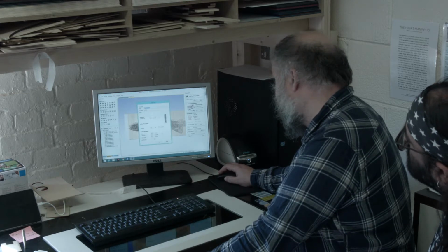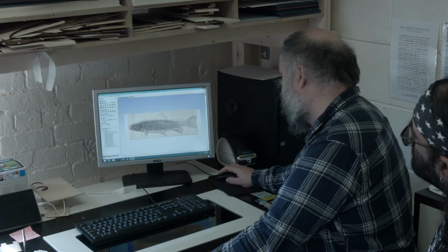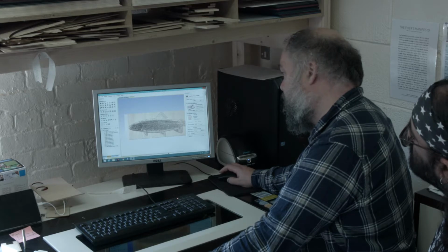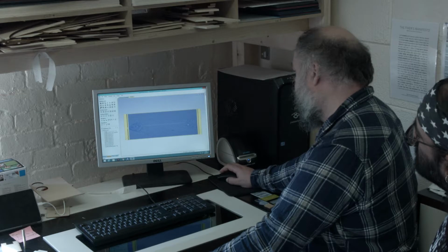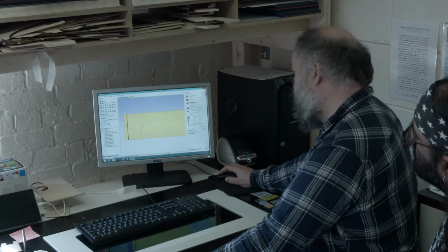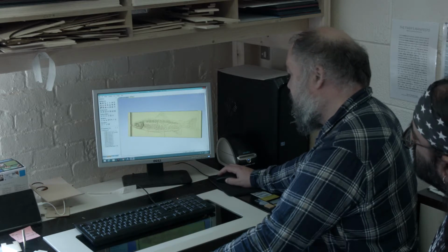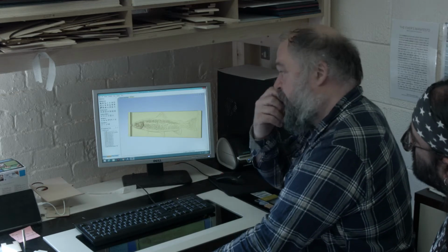I'm going to edit that down so it's just 1mm. And hit calculate. And then again, preview all tool paths this time. Cool. And you can see it actually shapes it up. I've got other tool paths selected, which is why you've got the borders, etc.